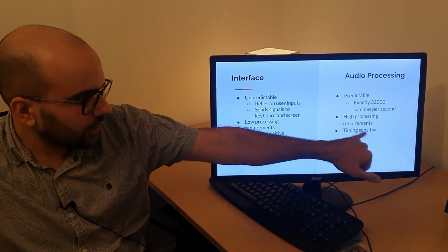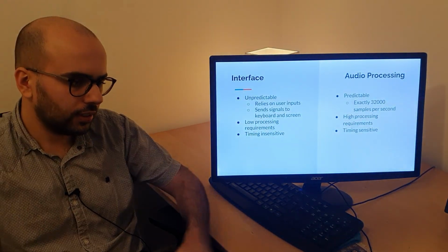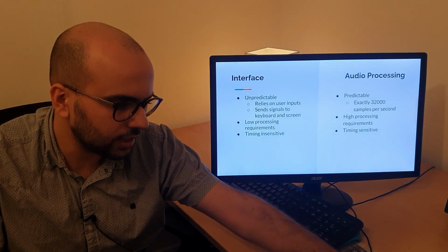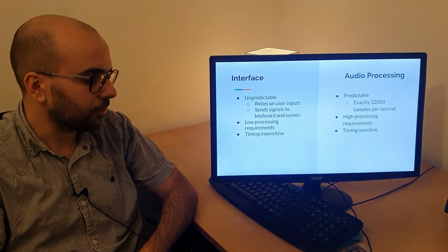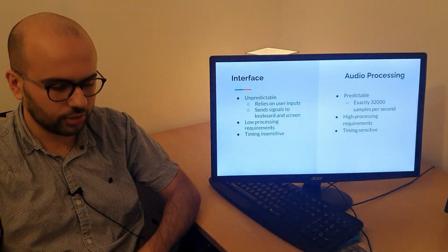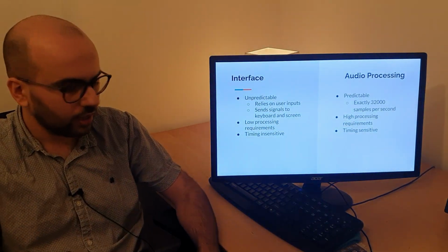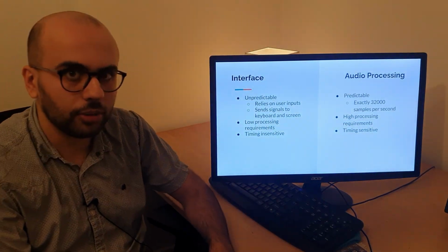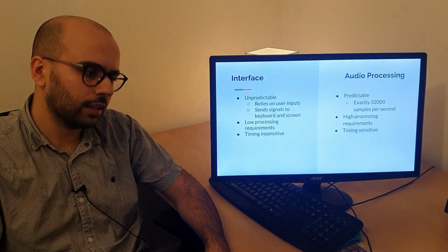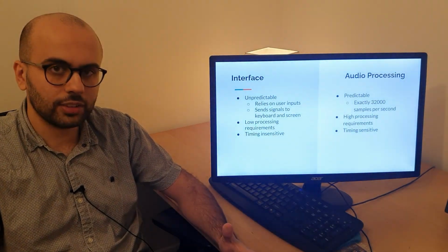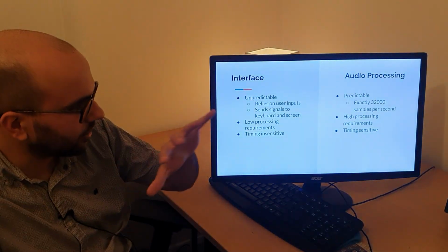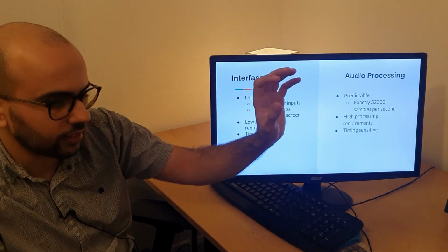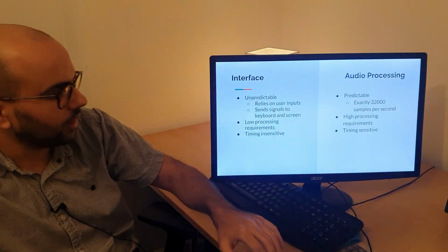And it is extremely timing sensitive, which is, in contrast to the interface side of things, if there's a delay of 5 milliseconds, that can ruin everything because you need to have your samples ready the moment that the DAC wants them. And if you don't have them ready, what you're going to hear are a lot of glitches, and it's going to make a lot of weird clicking sounds. So you really need to make sure you have all these samples calculated in time. So it's extremely timing sensitive.